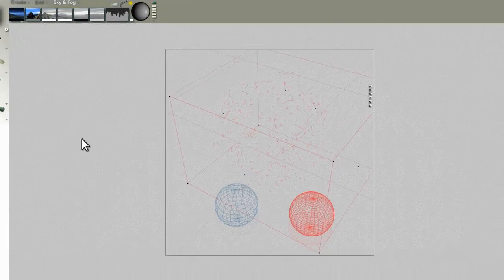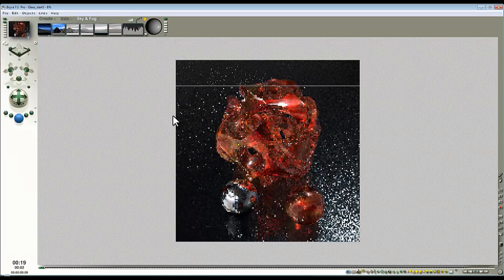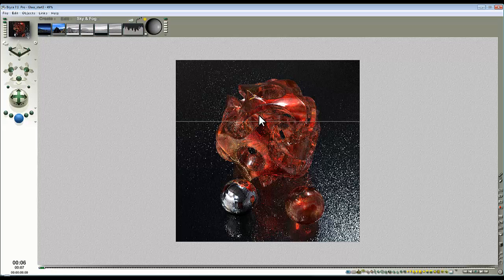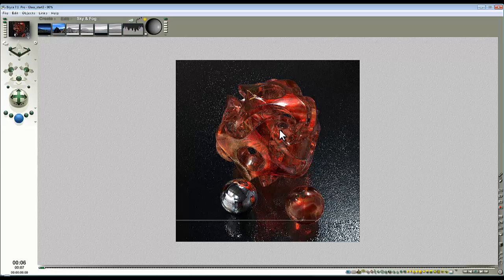So if I have a look now, it's looking quite a bit brighter. So the anisotropic effect is coming through generally through this material, lightening it up. We've got the transparency and the lightness is being seen through the material, but we don't really have any impact like we had before from the anisotropic highlight. We've got some nice reflections provided by the HDRI image, but we really want that highlight back in there.